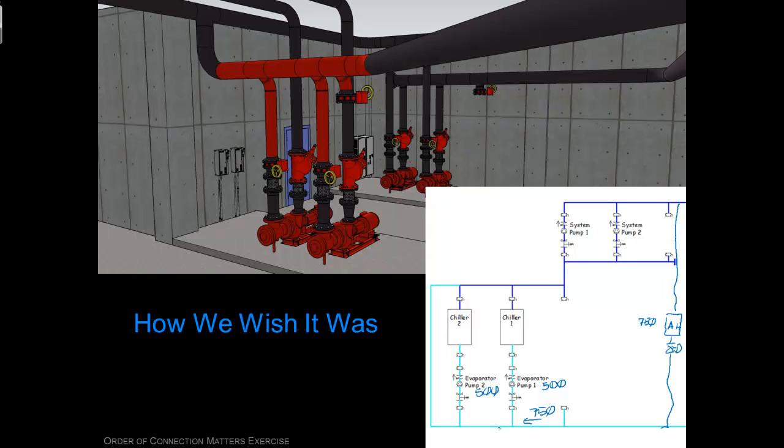You get to this T, this piece of pipe. If we took 500 away, that means in this piece of pipe there's 250 GPM going this way. When we get to this T, again, since we can't create or destroy water, the only way we can get the 500 that's going to go through that chiller is for 250 GPM to recirculate through the bypass.